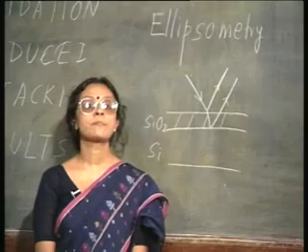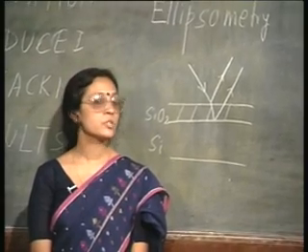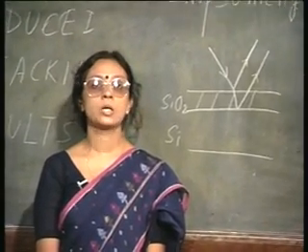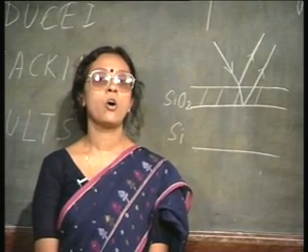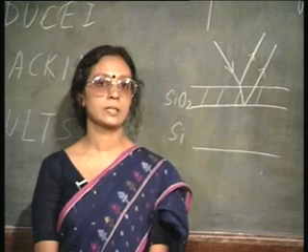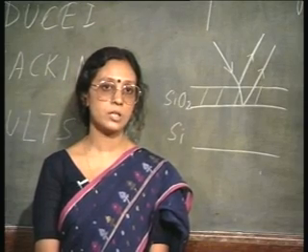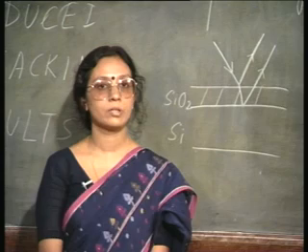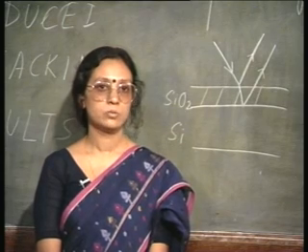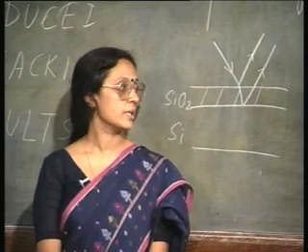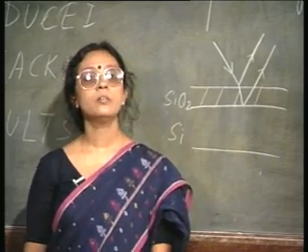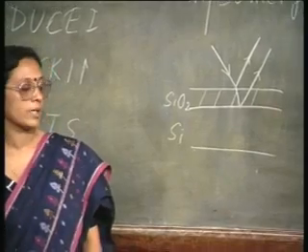But even here, the path difference will repeat every 2500 angstrom. So, that means that one has to know the order of magnitude of the oxide thickness, whether it is 2000 angstrom thick or 4500 angstrom thick. Within this 2500 angstrom limit, the oxide thickness can be determined with a very large degree of accuracy.